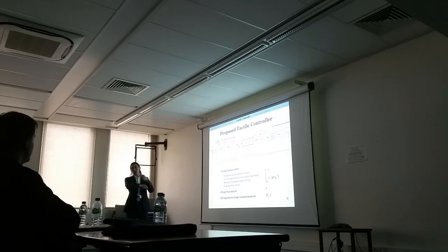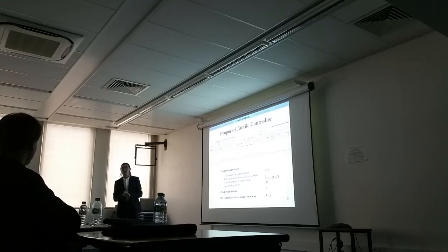But it's not a real Jacobian as in robot arm control, where changes in joint angles are mapped to some other space, which is Cartesian space. However, this is a feature space, that is a contact frame space. And this is not a Jacobian. This is the interaction matrix, I would say, as in visual servoing approaches.